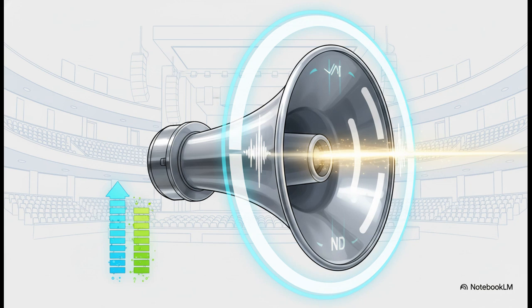Because it acts as an acoustic transformer, perfectly matching the impedance of the voice coil to the air, the efficiency absolutely skyrockets to approximately 40%. The signal-to-noise ratio is a pristine 40 decibels, with a vast, flat response from 25 to 10,000 hertz. Interestingly, directivity behaves differently depending on the sound itself. It's omnidirectional at low frequencies, but forms a narrow, highly concentrated cone at high frequencies. Due to their immense efficiency, they are almost exclusively used in public address systems and massive auditoriums.